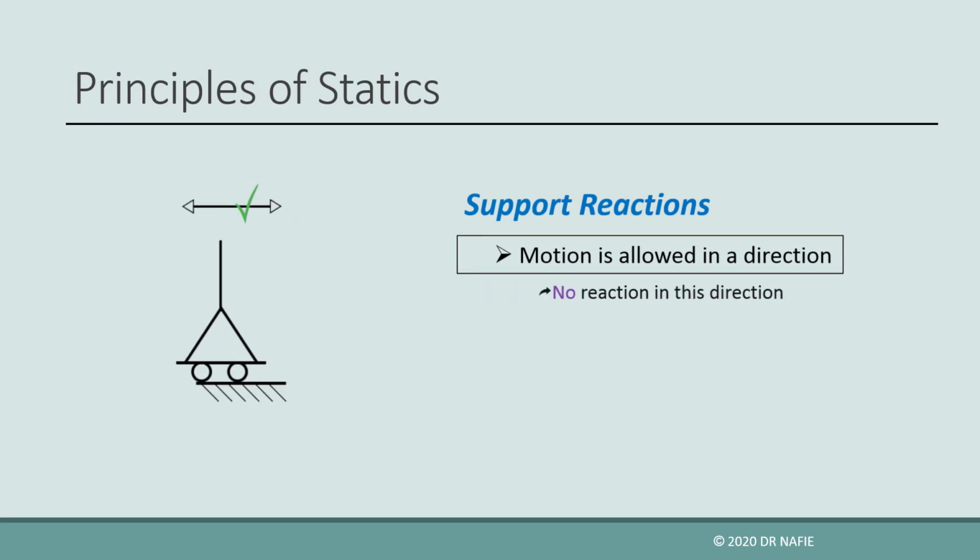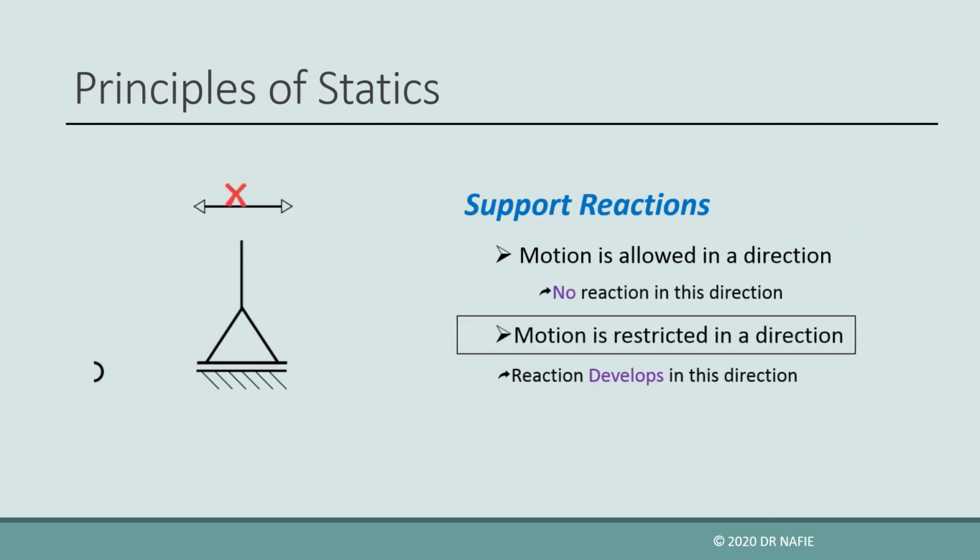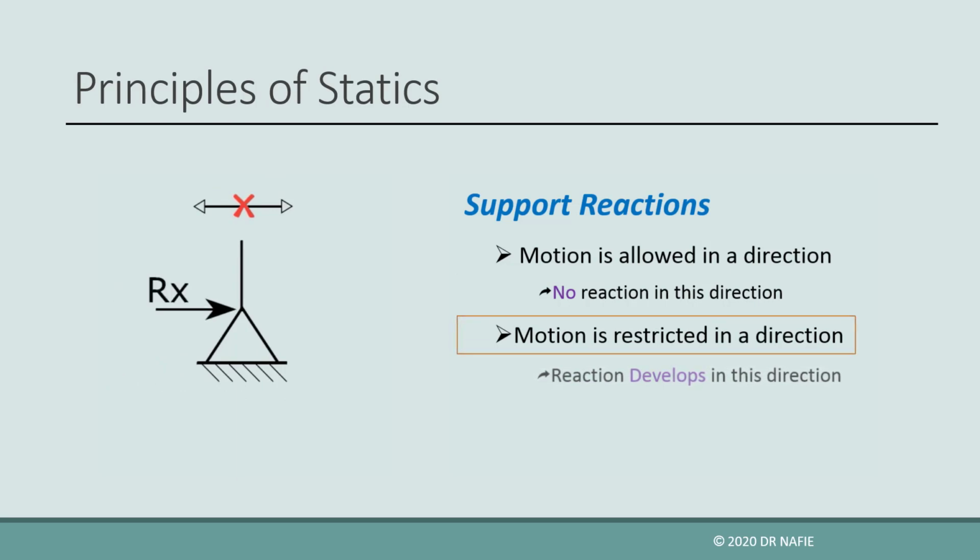For any support, when movement is allowed in a certain direction, no reaction develops in that direction. A reaction will develop in any direction when motion is restricted in that direction.